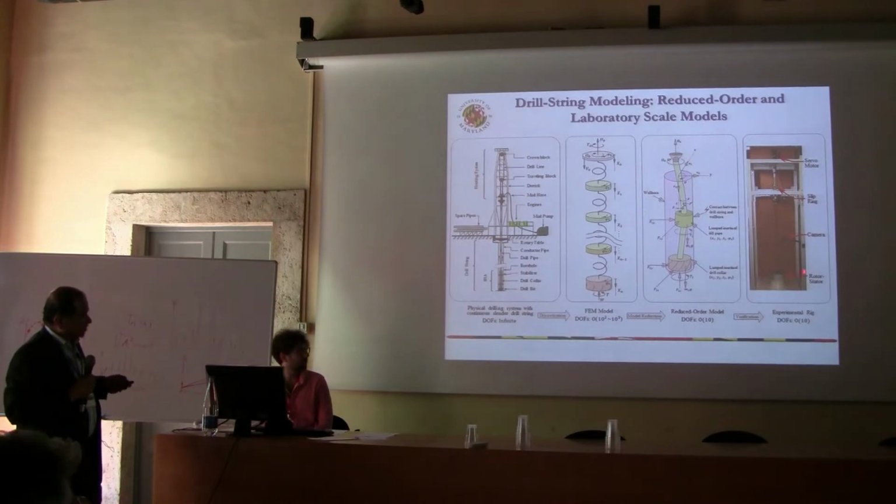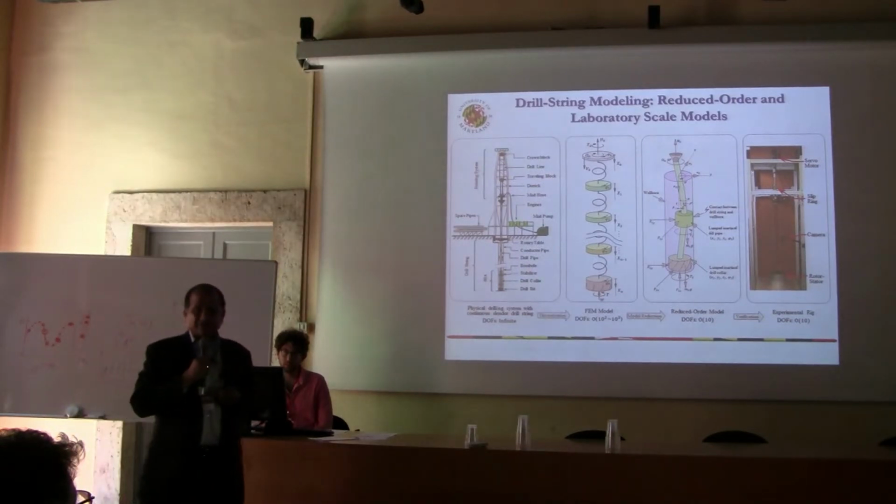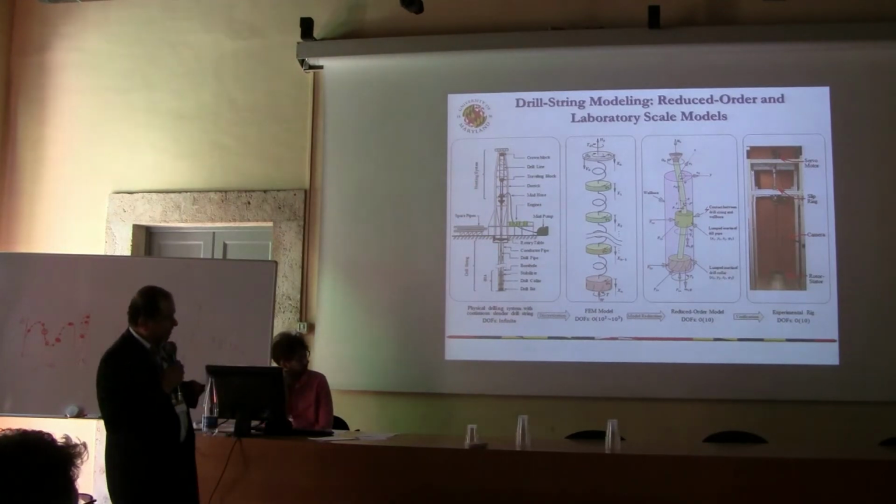So here we have a rotor-stator arrangement to mimic what you see out here in essentially a bore well, with a thing that rotates at the bottom, and then we have a slip ring for strain gauges instrumented on the string, and a servo motor through which we provide the rotational inputs to the system, and a camera to pick up the motions of the disc itself, which one could use to look at eccentricity as well as contact and loss of contact type of motions.